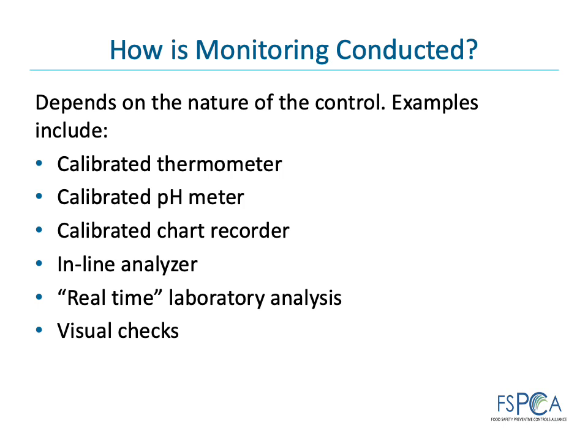Monitoring should be designed to provide rapid, real-time results. Some laboratory methods are relatively quick and can be used for decision-making. For example, pH measurements are useful to monitor fermentation processes. Viscosity measurements may be useful for processes that require specific flow characteristics for an effective heat treatment.